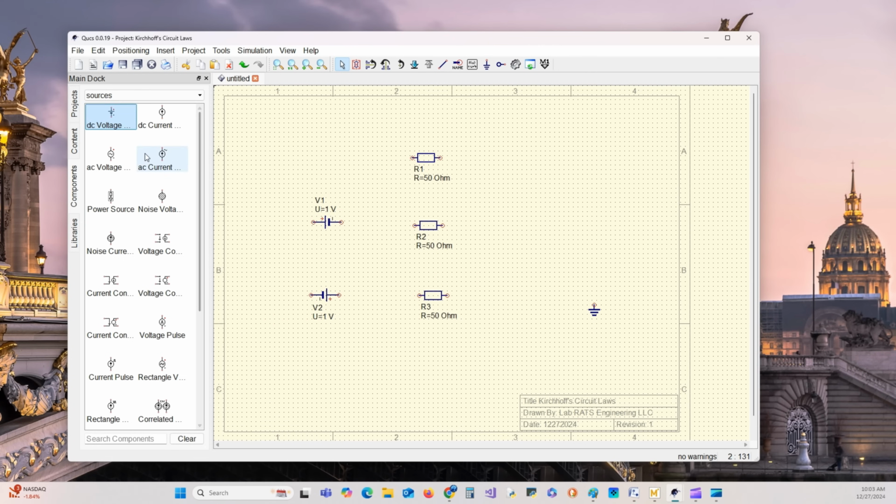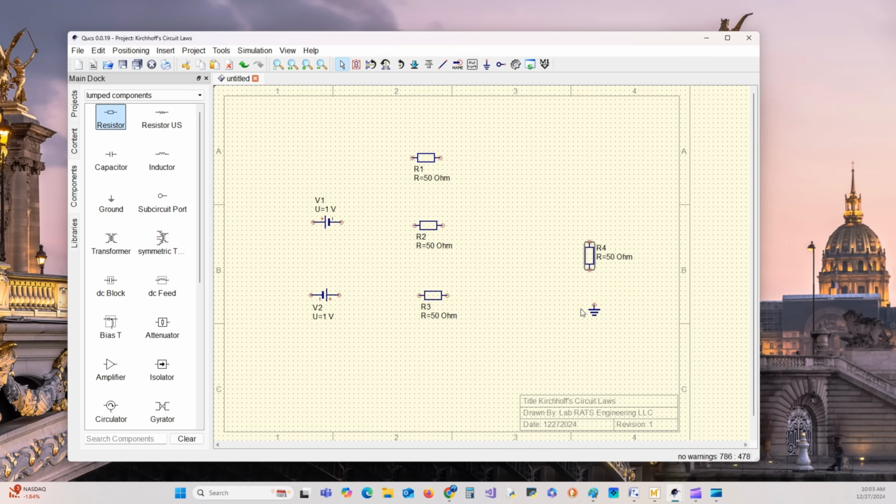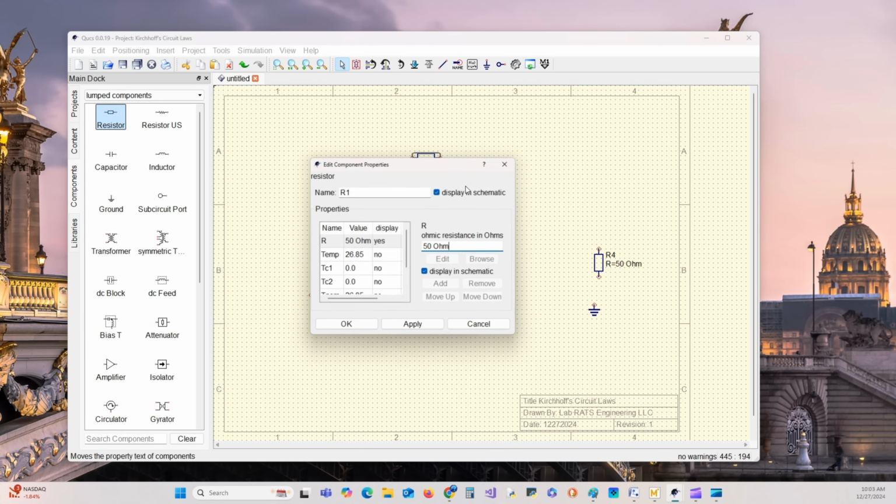We need our other resistor for the biasing. This is going to be such a large resistor that very little current will go through here, which will give us a small error. Okay. Now we know that R1 is 100 ohms.